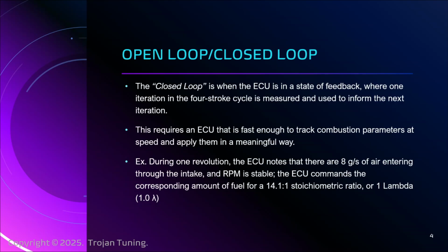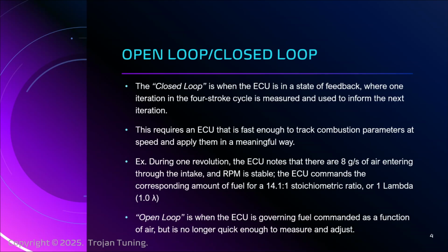So this calculation occurs, right, where the air coming into the engine is known, it is metered, it is measured, we know exactly how much is there, we know the stoichiometric ratio we are shooting for. The computer can then calculate or derive the corresponding amount of fuel, and you put the two together and off they go into the cylinder, right? This is all measured, right?